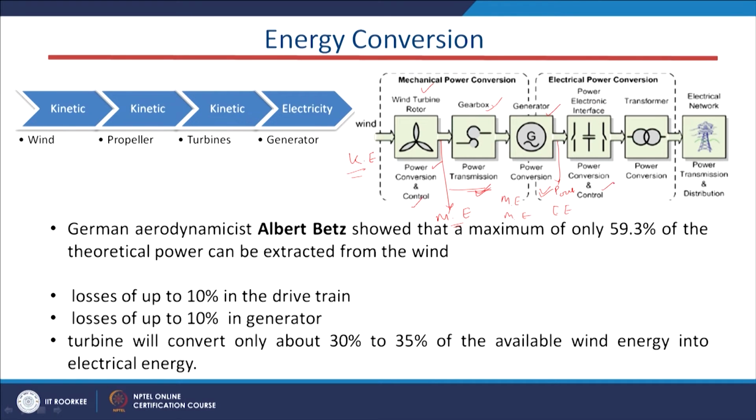And after that the AC signal will be connected to our power system through a proper step-up of the voltage, and of course, because we have to match the frequency and voltage of this particular grid system, we have to synchronize the wind energy system with the nearest grid.